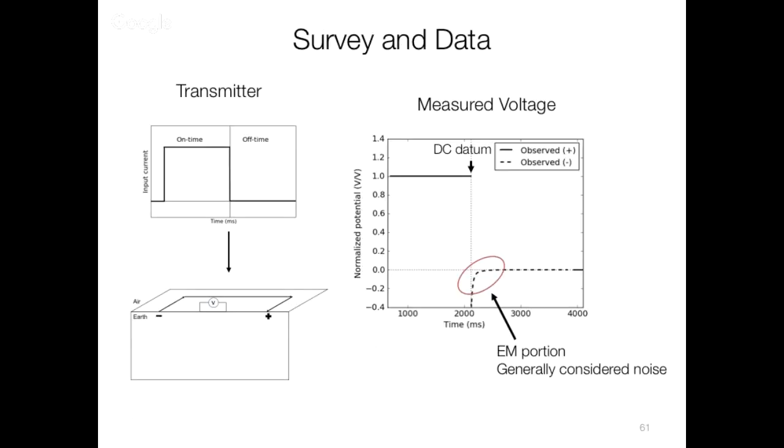Here's a case where we've got on-time data for our resistivity experiment, we're going to work in a horseshoe type of environment, and we're going to turn the current off, and then the voltage that we're going to measure is actually something that's going to go down. It's going to go negative, there's going to be a transient, and then it's going up.